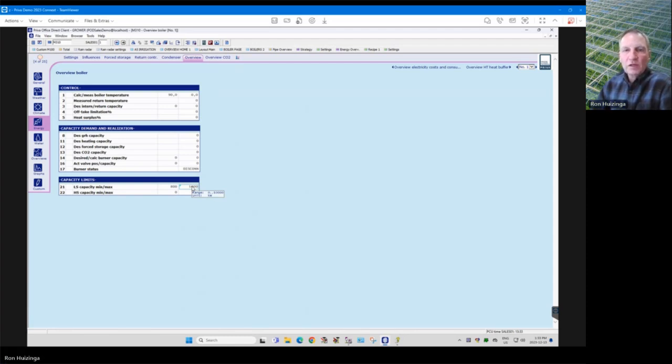And so when we get a CO2 demand from the greenhouse, because the CO2 is dropping below the set point, it'll come on and put a kilowatt number here to run the boiler. And if you make it aggressive enough, it'll run the boiler at full speed if you want.